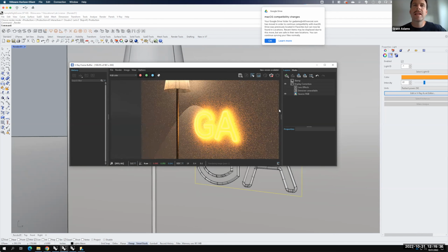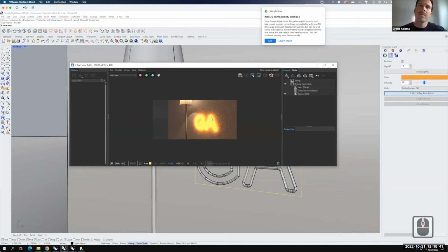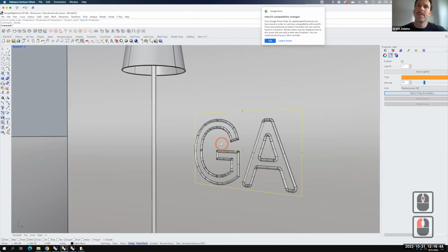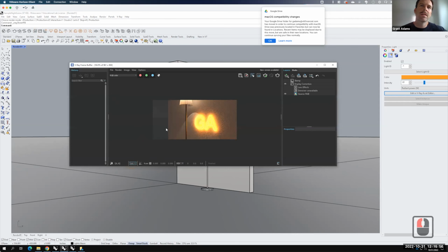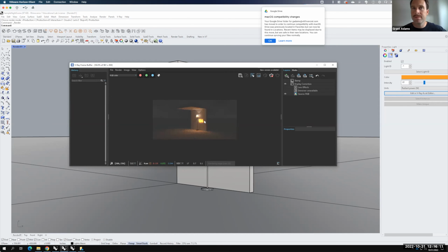All right, so now it's pushing that light away. I think my intensity is still too high on these, but if we back up a little bit, actually I need to back up to right about here, and when we were to render, you'll see that that orange light is being cast out a little bit more into the scene because of that rectangular light. Come on, let's render again. There you go. You can see the little dots, the orange dots being cast out here. Those will refine into a much better light condition. So that's how you would do some kind of a neon light.